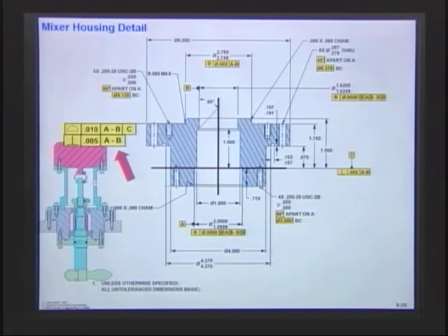Well, first of all, remember on this first joint, joint number one, when we initially toleranced this part, we had a datum reference frame. Remember the datum reference frame was in black, and on this top face, we said that face could move up and down within 10. That's where we had our profile tolerance within 10. But then we said that also it could be off perpendicular within 5, and we allowed that face to tilt relative to the datum reference frame. And the datum reference frame is really where the shaft and the bearings and everything goes in.